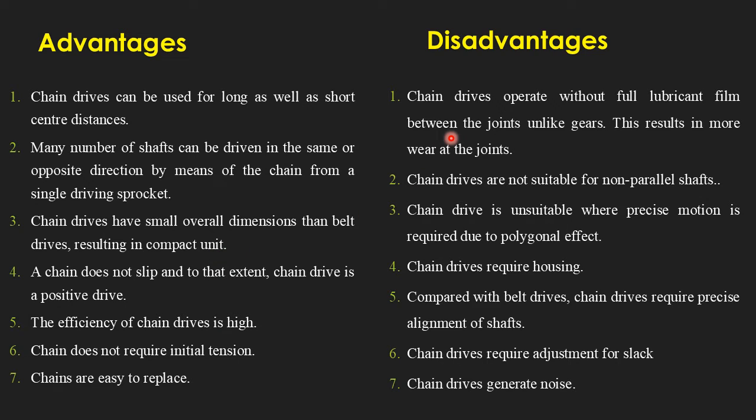Regarding the disadvantages, if you compare with gear drives, gear drives inside a housing will be operating under full lubrication in major applications. But chain drives do not operate under full lubricant film between the joints. There is no presence of full lubricant film.